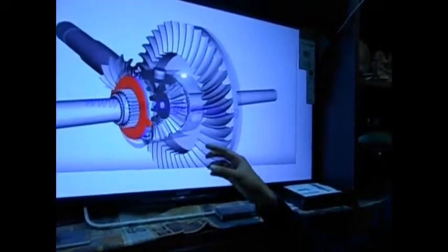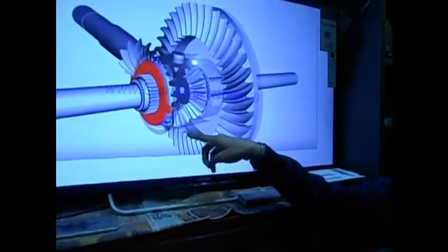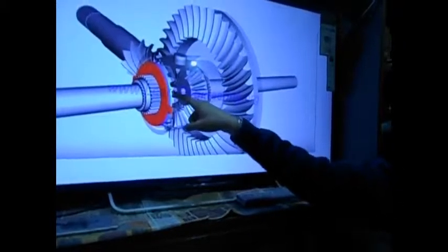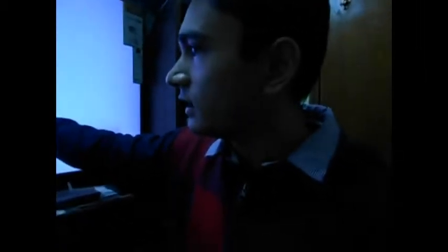The limited slip differential makes use of the property of bevel gears. Bevel gears used in the spider gears as shown here and the left and right side drive gears have a special property. When a bevel gear spins, it not only transmits power in the tangential direction, it also transmits power in the axial direction. This leads to the left side gear axially moving away from the spider gear as shown here.